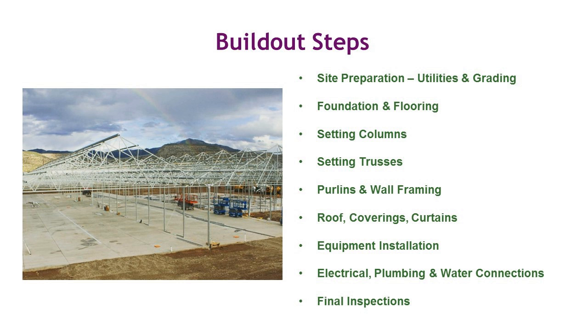Moving on, though, foundation and flooring. As we discussed here, you could either do a footer, pour caissons, or pour a slab, and that's going to depend on your budget as well as the loadings. Next, setting the columns. This is a picture of a facility that's already had the columns, trusses, and purlins set, but setting up the columns goes pretty quick, and then the next step would be to set the trusses, and then lastly the purlins and the gutters.